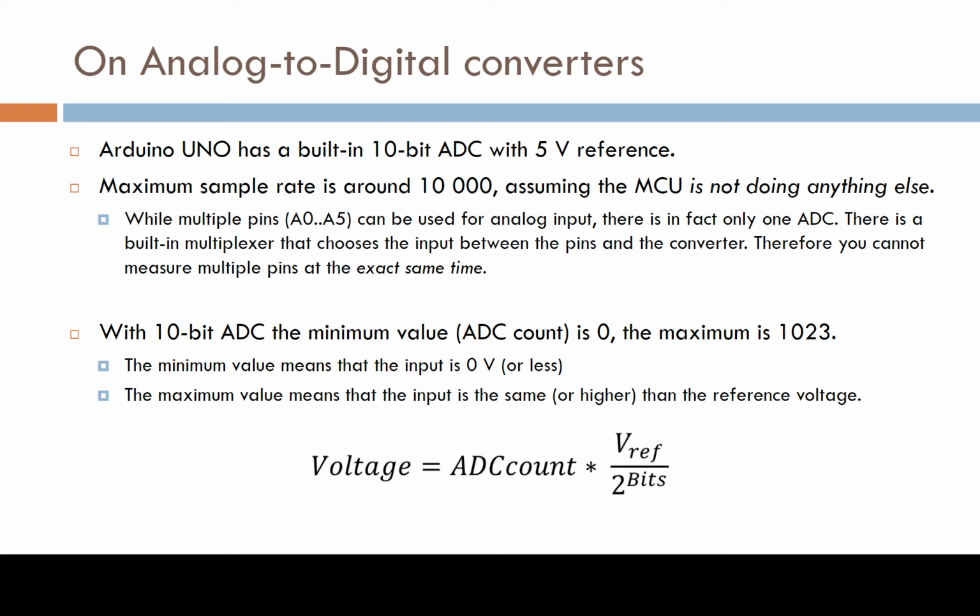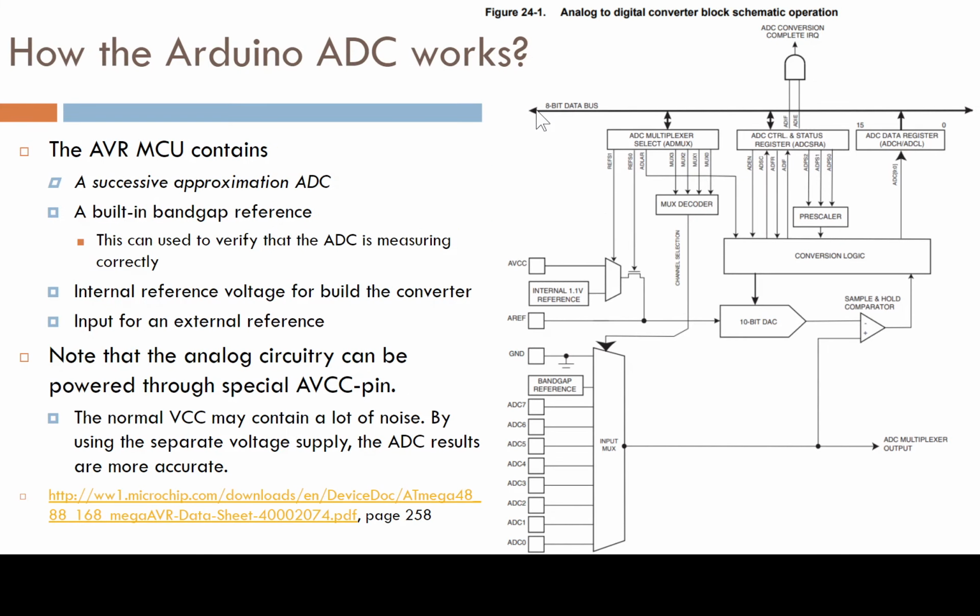And it actually even can break the chip if that happens. But anyways, the Arduino A2D converter. It's a so-called Successive Approximation A2D converter, and it's quite genius actually.